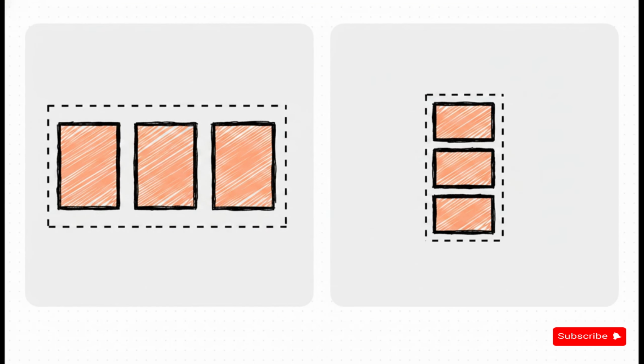So there is a very exact trade-off at play here between the two. With legacy FinFET, if you need more drive current for performance, you literally have to add more physical fins side by side on the chip. That eats up precious real estate and totally limits your overall density. But with GAA, it's a game changer.